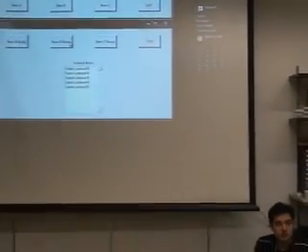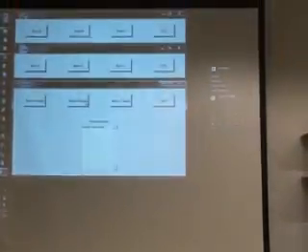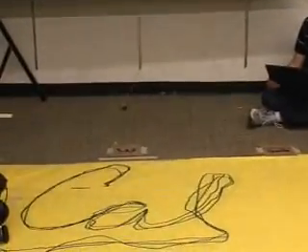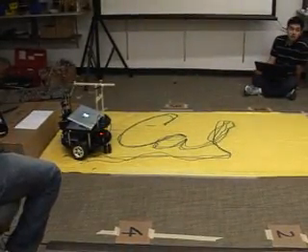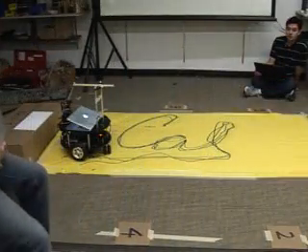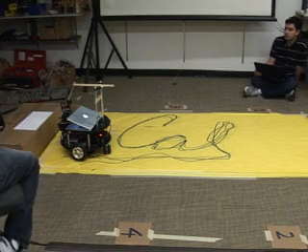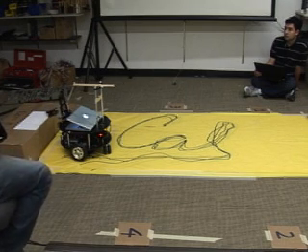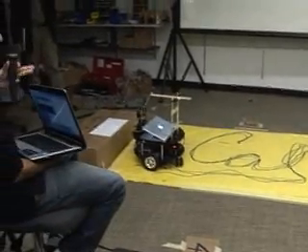So right now the kitchen is going to tell the robot that order B is ready for 4 orders of B already. So the arm will now pick up 4 foods. Right now, the way that the path planning is set up, it's going to basically make the arm pick up as many times as there are requests it has to service. So as you can see, the arm will pick up 4 times for the 4 requests that were serviced.